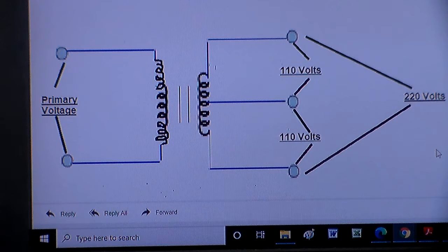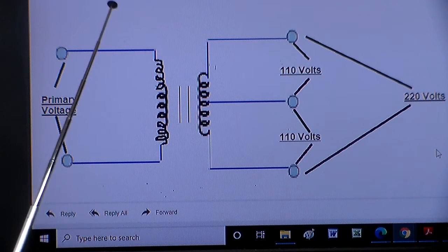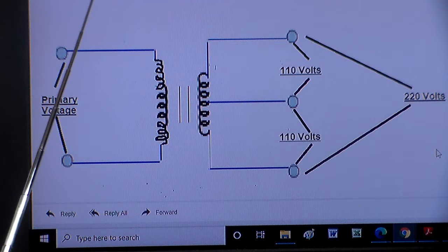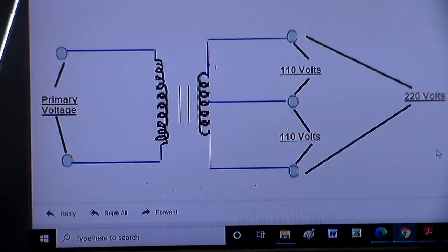The primary voltage is much higher, and it's really not part of this, but the reason is it's easier and more efficient to send AC voltage at higher voltage and lower current. So when it's out on the pole and before it gets to your house, at some points it can be very high. And what happens is when it gets transferred, power is equal in a transformer, which means if you have the ability to do, say, 1,000 watts here, it can do 1,000 watts there.